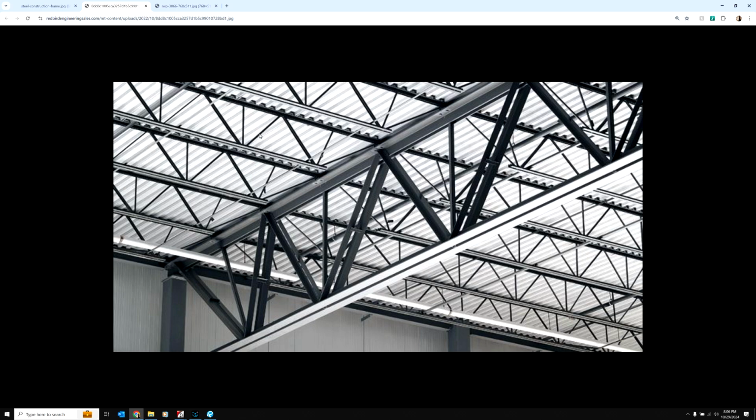The thing to keep in mind with open web joist is we have what we call A's and V's. And in new buildings, your V's will pretty much always have a vertical piece of steel that blocks our access to run dead center. And ideally, when we're laying out lines that have to run through a bar joist, we want to hit the very center of the A and the V so that we know we're good and clear of the actual framing for this thing.